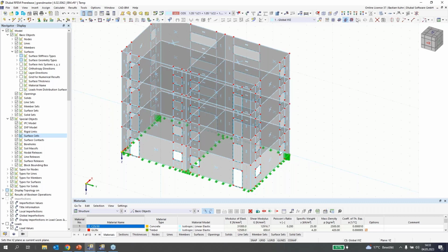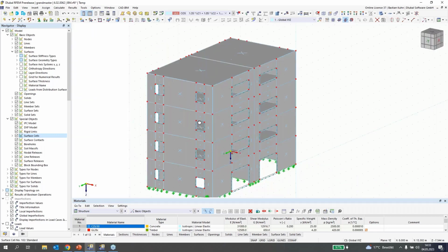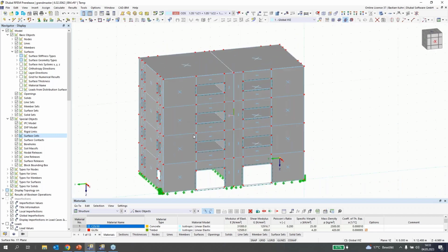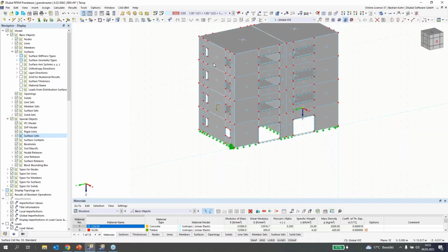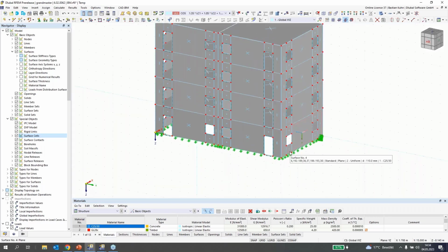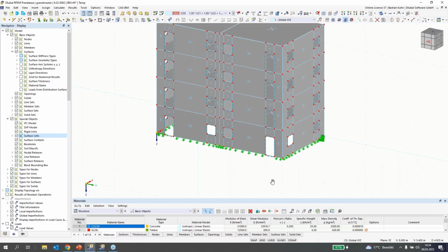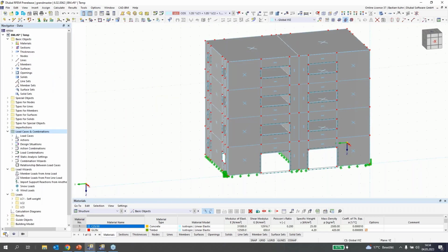If we look for this building, and we can maybe switch the other rendering on. Now, what is probably the most interesting part of this? I mean, there's these spandrels in here, top and bottom of each ceiling. That's probably interesting to be designed, definitely in the ground floor. And I mentioned it now already several times. The weak axis is the most design-giving surface for the wind load. So we probably want to verify the force that is going through this, and this cell. Everything else so far is really not my interest in here. I mean, we can, or you should verify them all, but it's really not necessary. And that's what the idea of this building model is.